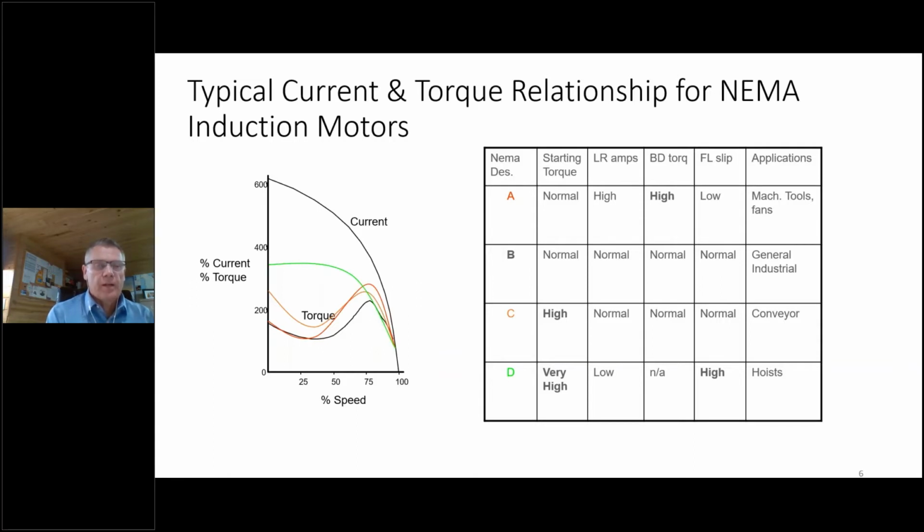And there's a normal value, and this is part of the NEMA MG1 design standard, that on a low voltage motor, you're typically looking at what they call an inrush current of about 600%. I'm not sure if everyone normally gets their head around that, but if you have a 100 horsepower motor of 575, and we'll talk about this in another slide, that's typically 100 amps. But when you're talking about 600% starting, this is where the electrical design engineers have to do their calculations to know how many of these electrical loads are coming on at once, and they have to provide enough power through the utility to start all these loads.